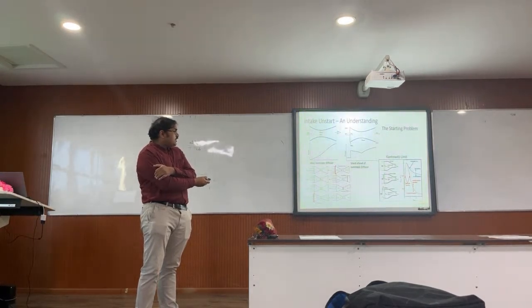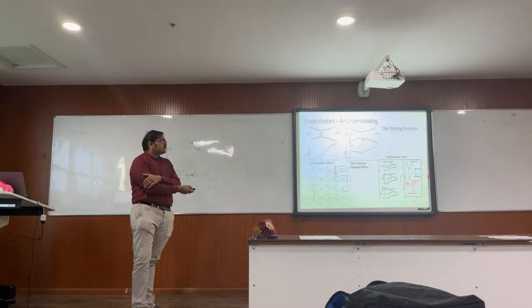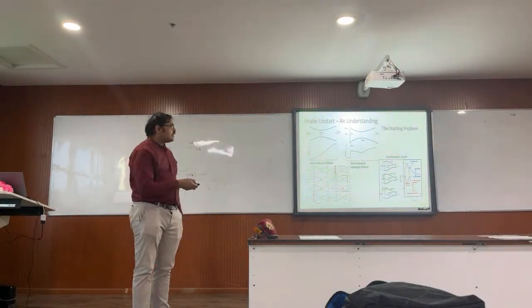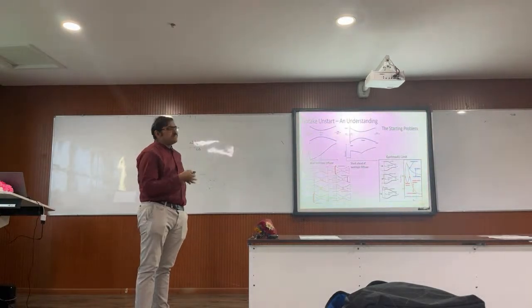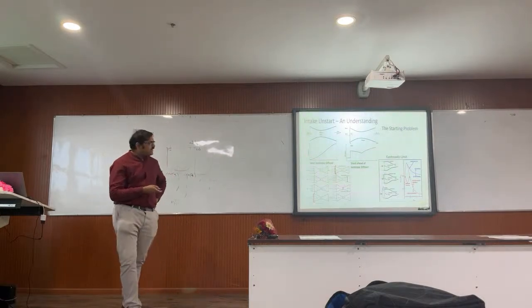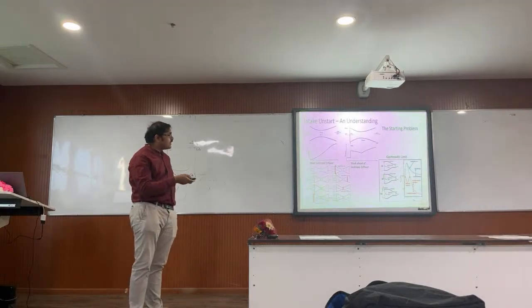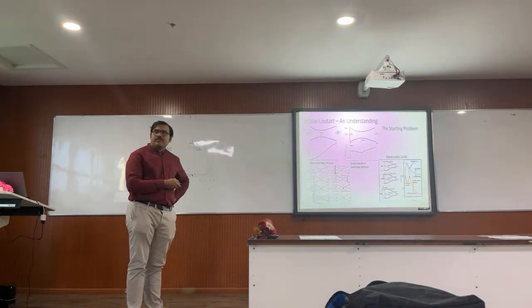While if the minimum area is exposed, it can also be written in terms of the area ratio. If the minimum area is below the isotropic line, then the intake will never start. And in between these two, there is a likelihood of them starting or unstarting. It's called the dual solution story. So this picture is important to carry when we go and see what we have done and what studies we have carried out. So, shall I move ahead from here?